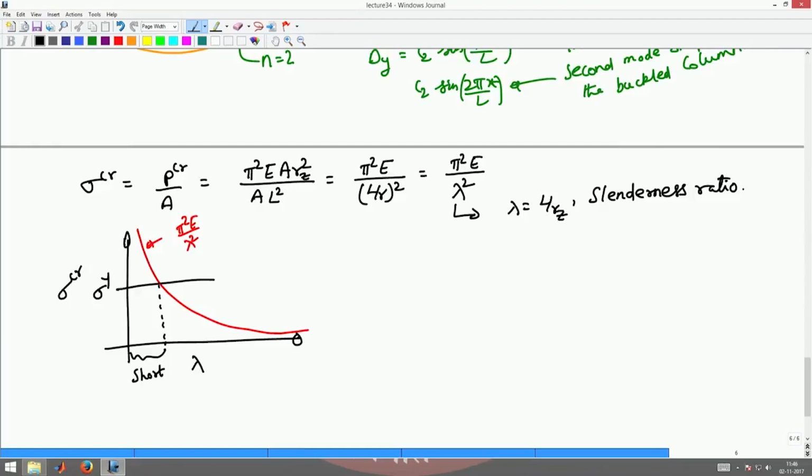It will have only the axial compression possible, there will not be a bending action coming in which will cause this failure. Okay. Axial compression will cause the failure. Once you cross this point, the mode of failure is governed by the buckling mode of failure or the stability induced failure, wherein the uncontrolled lateral deformation will govern this failure mode. Okay. So, this is what you have to understand.